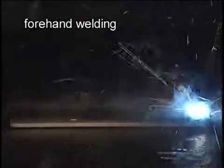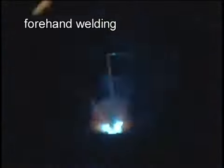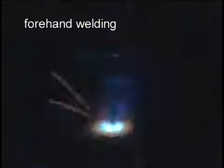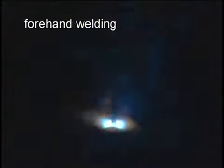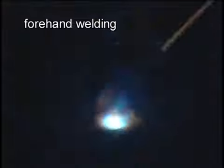In the forehand welding method, the molten weld metal is pushed ahead of the center of the generated arc. This results in shallow penetration, wider bead width, and flat weld reinforcement because the wire is being deposited into the molten weld metal, which makes it difficult to penetrate the base metal directly.